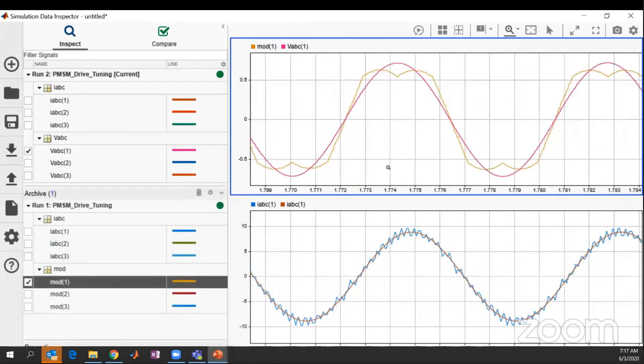As you can see, the difference is that modeling the switch level inverter will give you more of a double hump PWM output. And as you can also see, the switch mode inverter will give you a higher fidelity level, including some switching effects and nonlinear effects, compared to the average model.